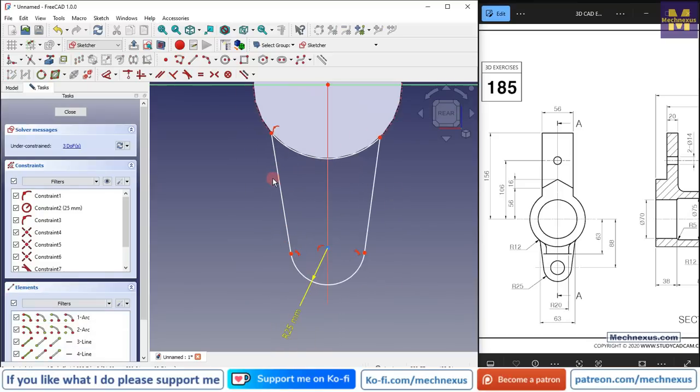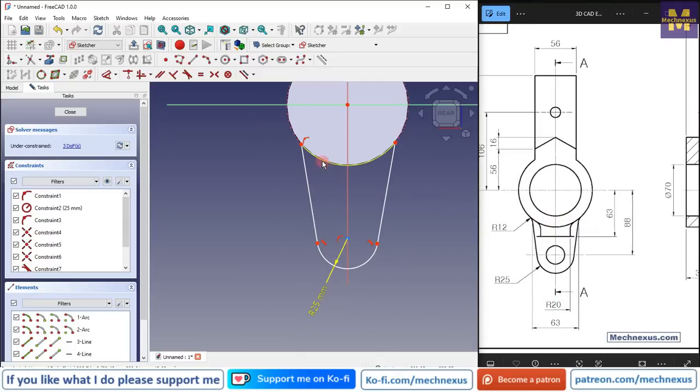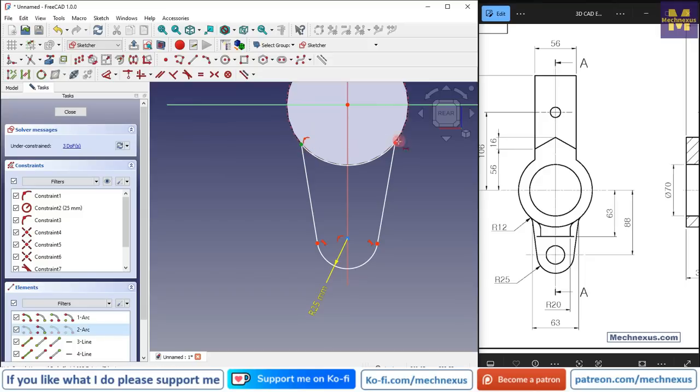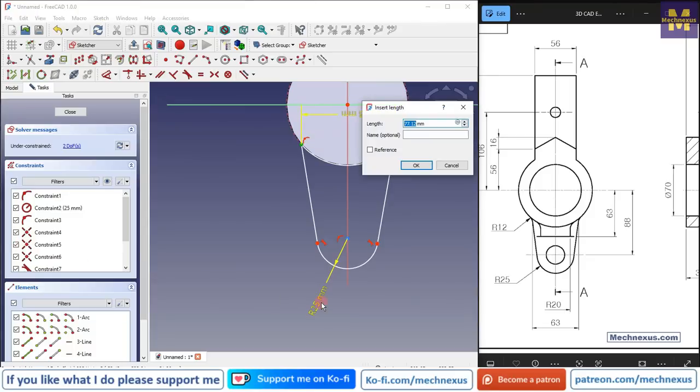And now if we see, this angle is not defined, so we will define it. So here is a 63, so intersection we will consider 63 here. So we will select a smart dimension and select horizontal dimension from this to this. Let the software define whether it is a horizontal or vertical.